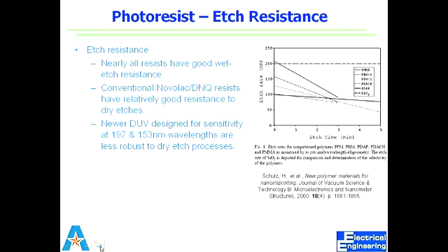But you have to see how deep we are etching. So if my silicon dioxide etch is 10 micron, then how thick of a resist can I spin there? Maybe some of them can give thick films, some of them cannot, right? So there are many more factors that come into this. That's why you need professors to go and ask.